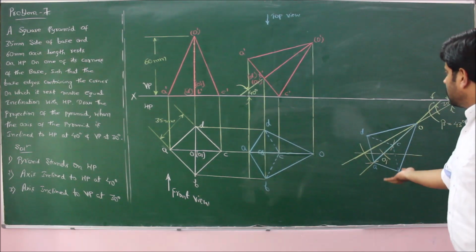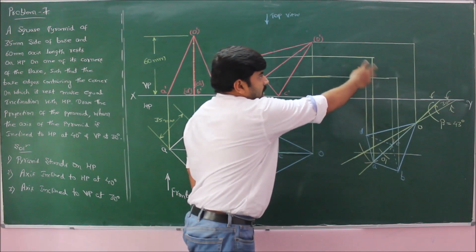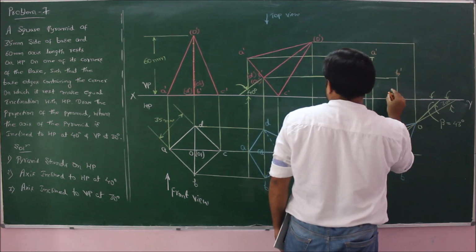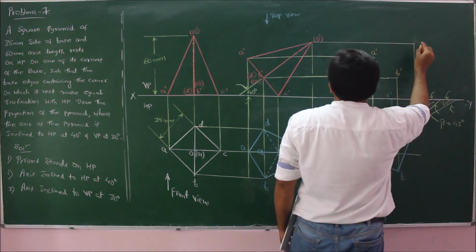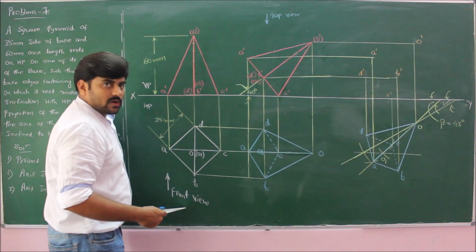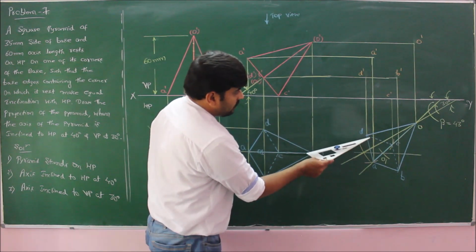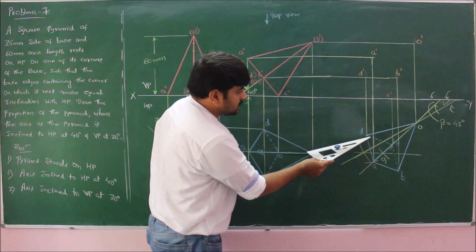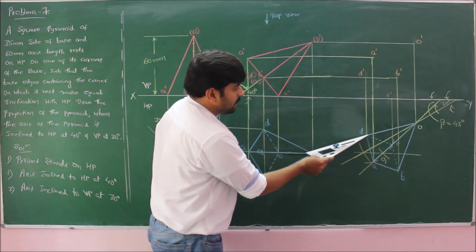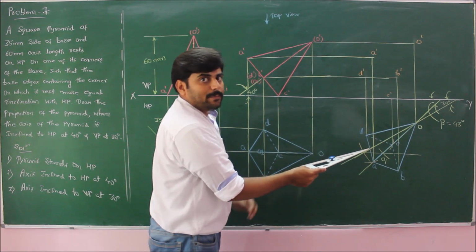Now take the projection vertically upwards and horizontal. Now mark all the corners. Now in the front view, the observer will be here. So to the observer, the farthest base corner is D. So all the edges emerging from D are invisible except they lie on the boundary of the pyramid.